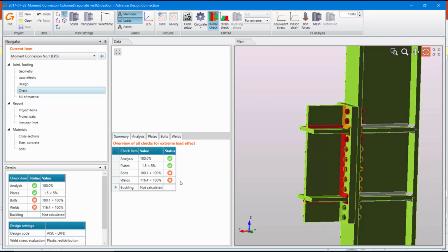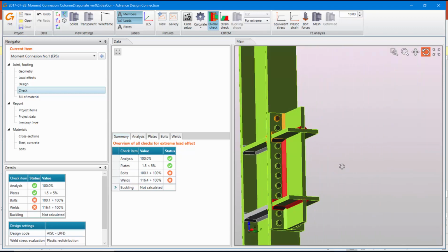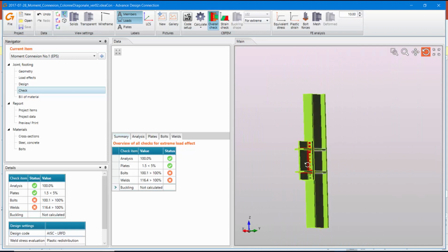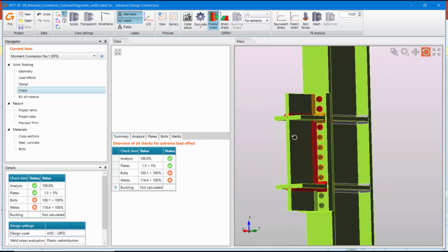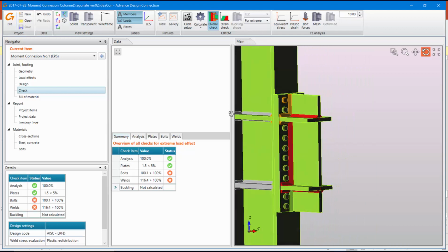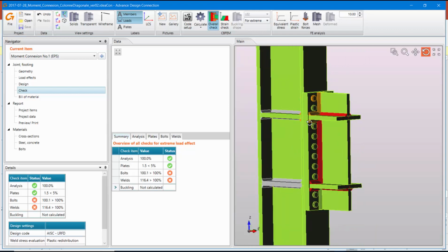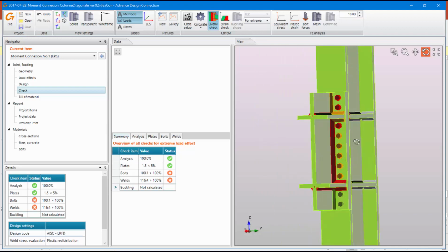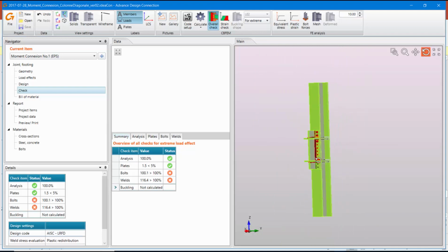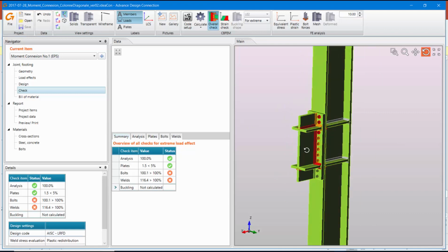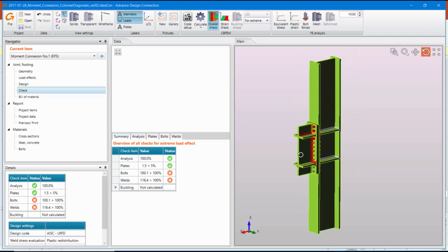And for example, for a preliminary design, as you see here, the bolts are almost okay. I have 0.1%. We have some problems with the welds, that the welds need to be modified. The software shows these results in color codes. Reds are not passing, and the oranges are almost passing. All of these colors are meaningful, and they depend on the design load ratio of each component.